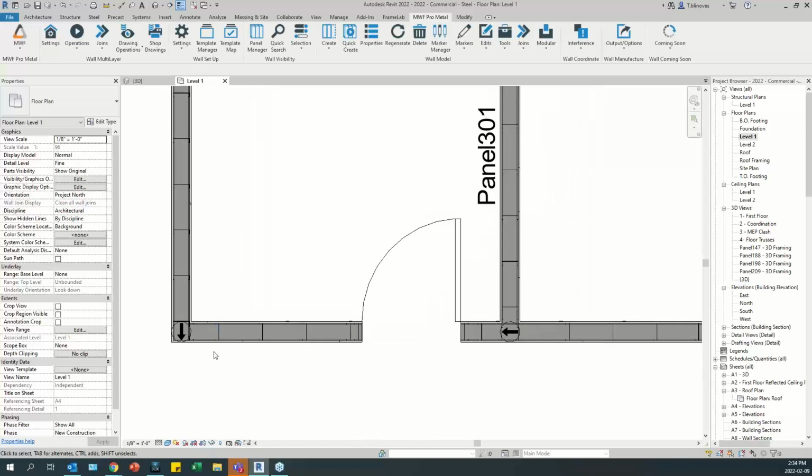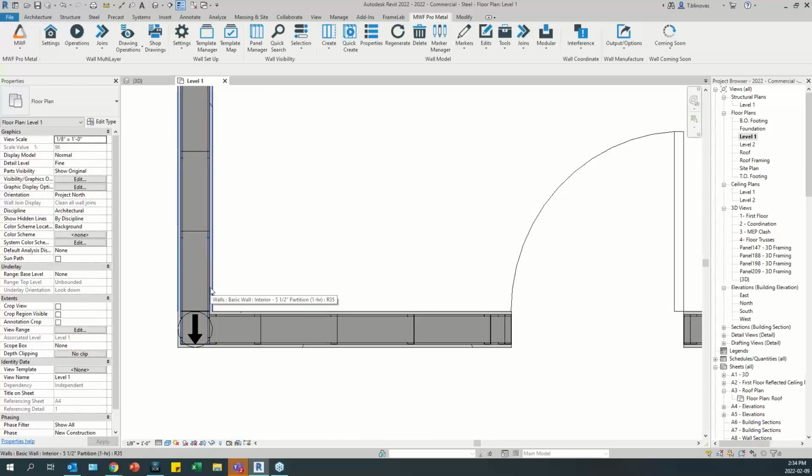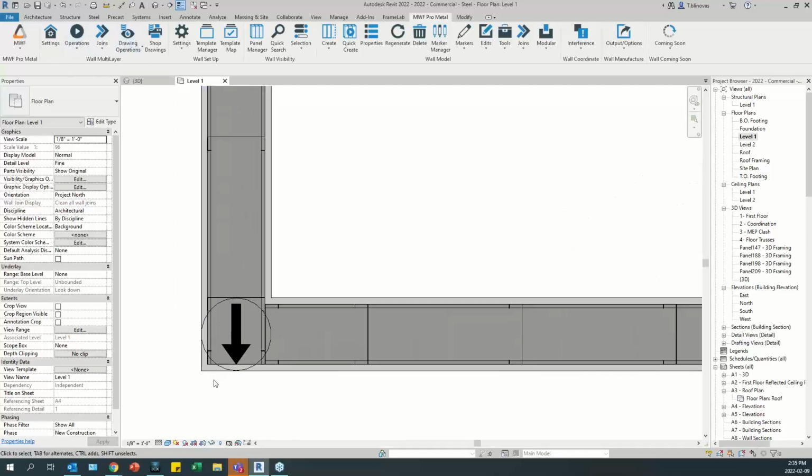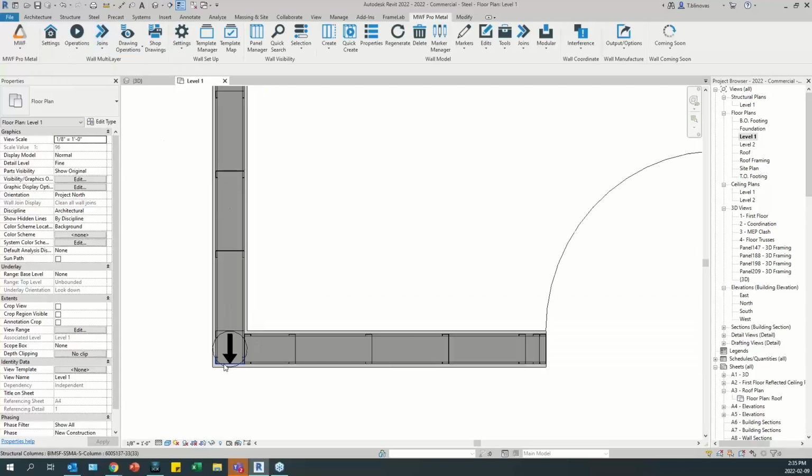Yes. So if you're going to have sheathing or gypsum boards, you're probably going to be using the multi-layer option. The way that I've created so far, we're just using what we call standard panels, so we're just focusing on the structural layer. If you do have gypsum as well, you could create the panels using the multi-layer option, which will automatically also create the gypsum. The process will be exactly the same. You could still just use the joins for the structural layer, and then we have this separate one here only for sheathing. Okay, so you could use that.